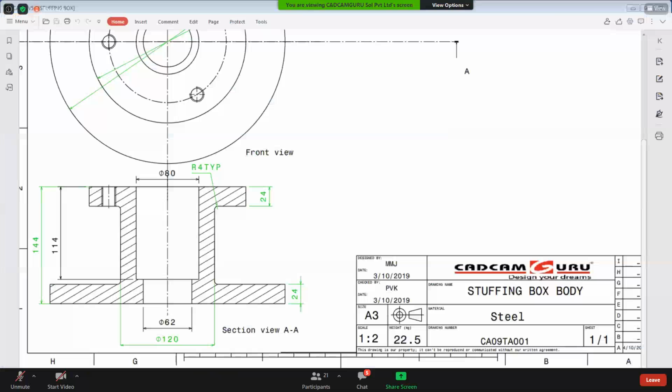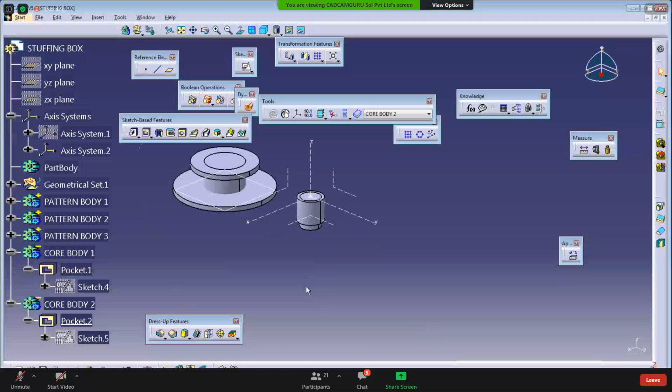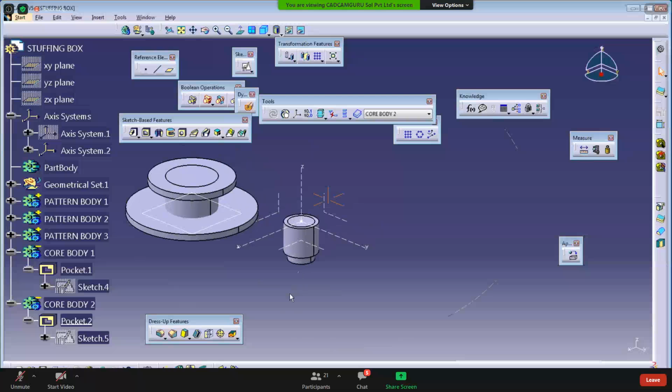Then next, there is a hole here, right? That is directly a threaded hole. That is a benefit of this methodology. In the earlier example, last class, we discussed the structural way of modeling. There, in the Boolean operation, we cannot directly create the threads. For the threads, we have to cut the machining features only. But sometimes in plastic injection molding, threads are added instead of cut.